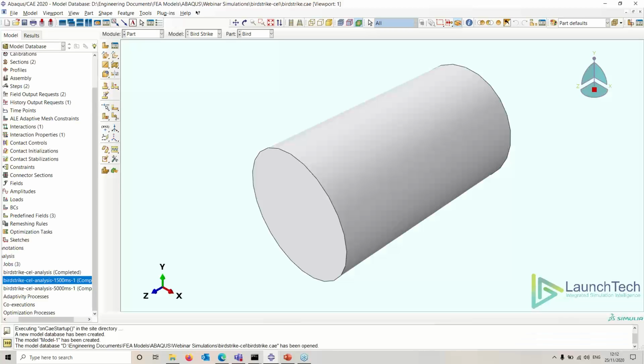Hi, good afternoon, everyone. I'm Rahul, and today I'll be explaining to you how to actually simulate the bird strike model on an aircraft using Abaqus Explicit. The case study for this is that we're going to use two birds that will come in contact with a double-shelled aluminum-based fuselage. And we will, as Melad explained, we will be using the combined Eulerian Lagrangian model.